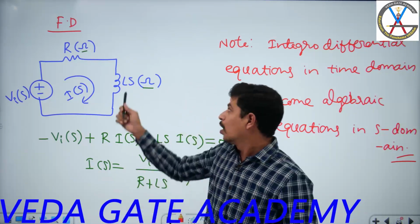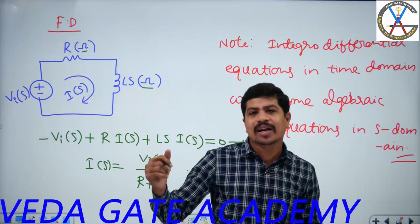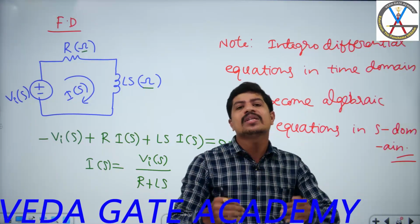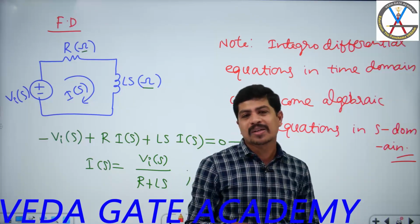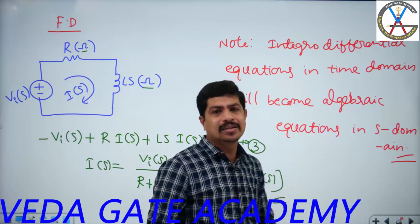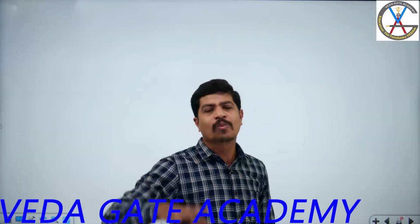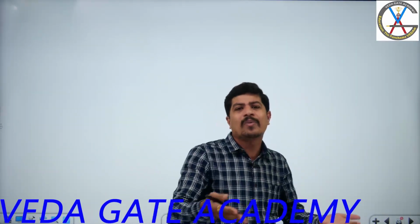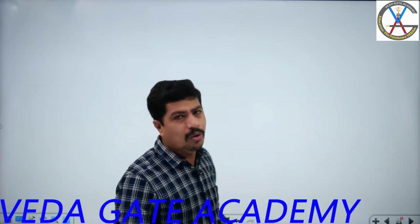As I have units as ohms and ohms, I can apply Ohm's law directly. There also I can apply Ohm's law, but only for sinusoidal inputs. If the input is sinusoidal, then L will be represented with omega L, and C will be represented with 1 by omega C, more or less the same. This is frequency domain analysis only. AC analysis is equal to frequency domain analysis. Why? Because the input we are giving in AC analysis is a frequency input, that is sin omega t. This is the advantage of S domain.